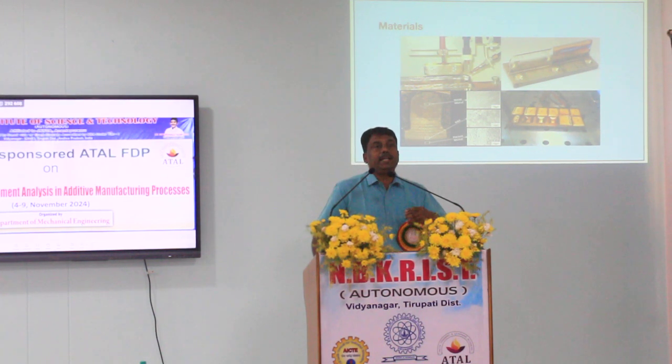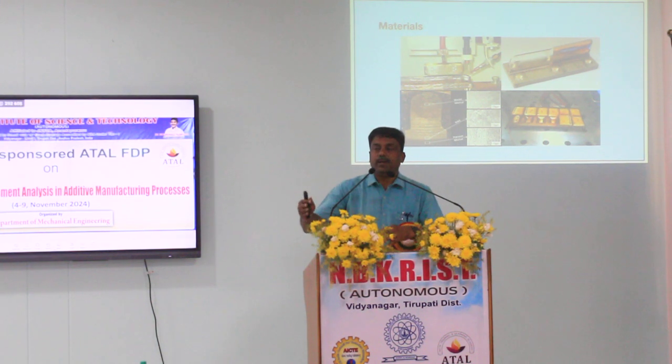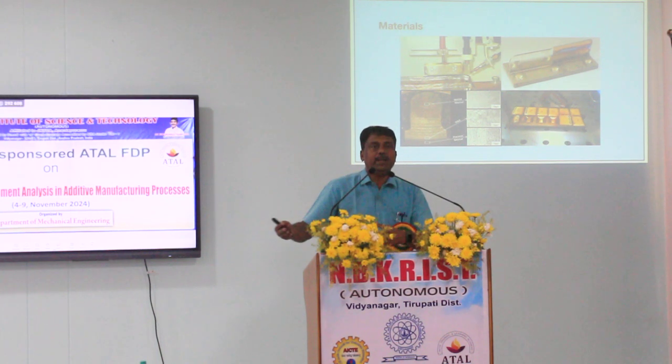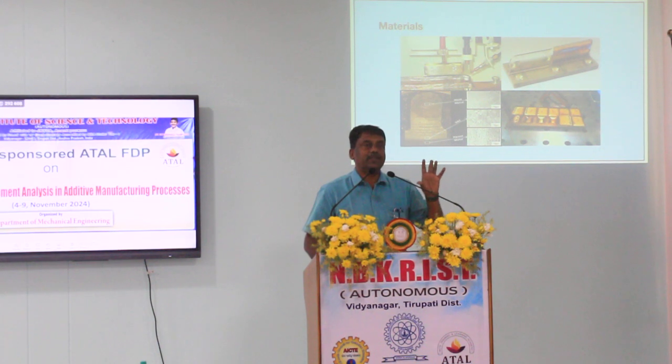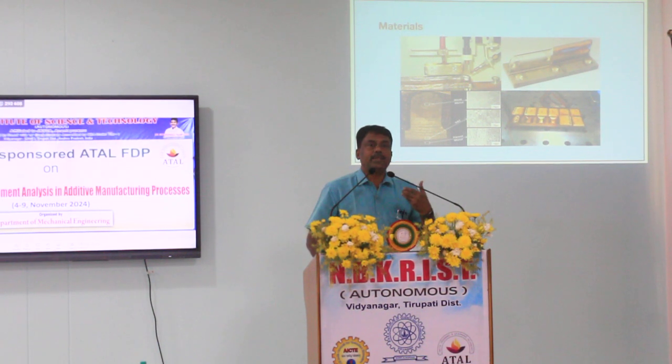So what are the materials we use here? Any material that is weldable can also be printed. That's a thumb rule. So any material that you see is weldable, we can also use that material for multi-pass deposition. So be it low carbon steels, titanium, even magnesium. In fact, magnesium, right now I was talking to Professor Siva, so I've been helping him to print magnesium AZ31 alloys as well. We can also induce defects to make foam magnesiums, right? Nickel-based alloys. So all these alloys which have very good weldability, we can also print them.